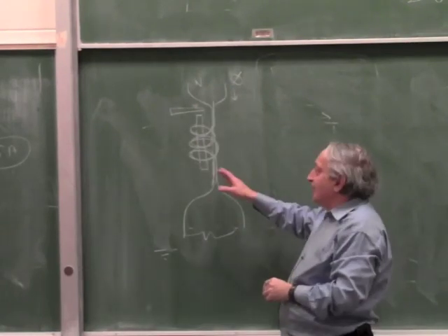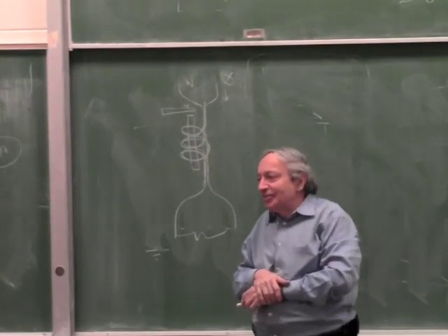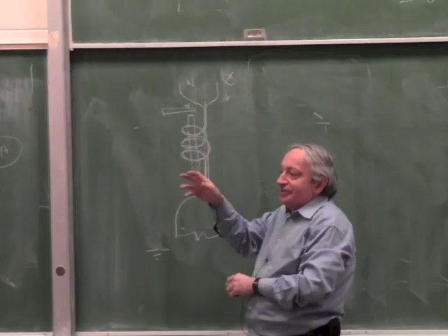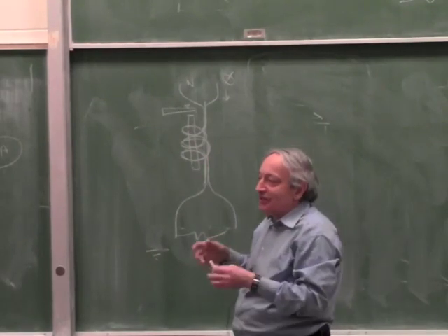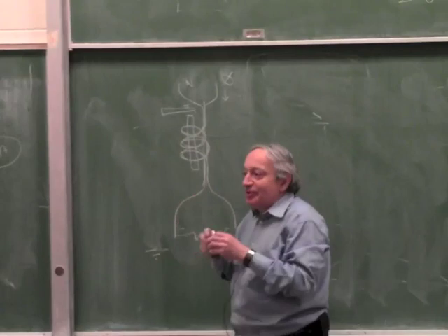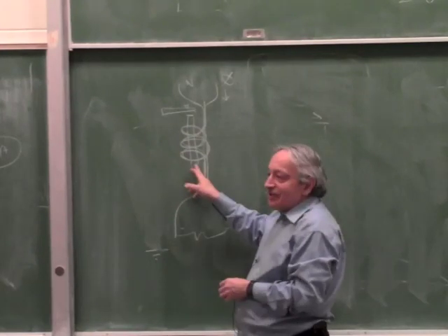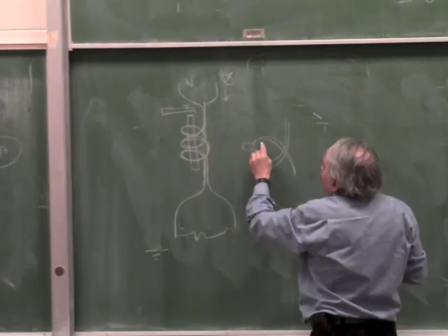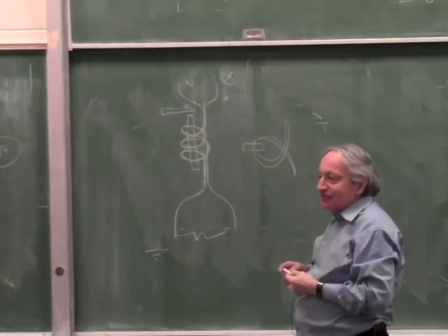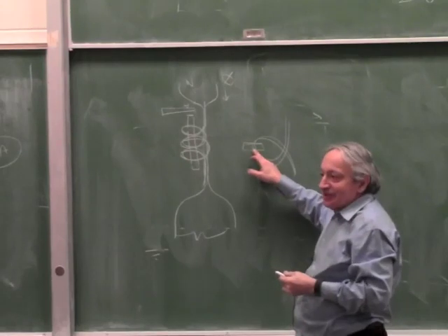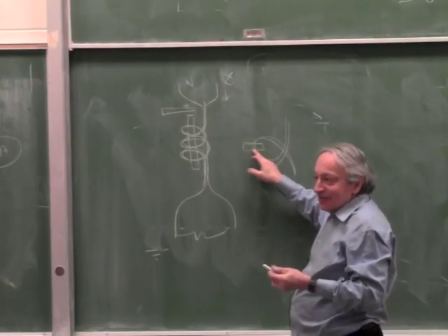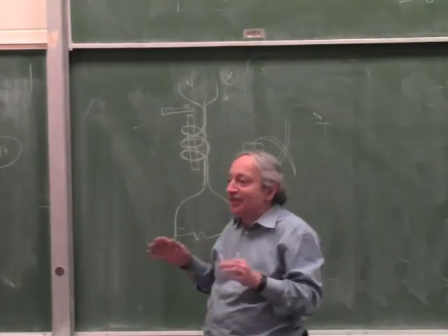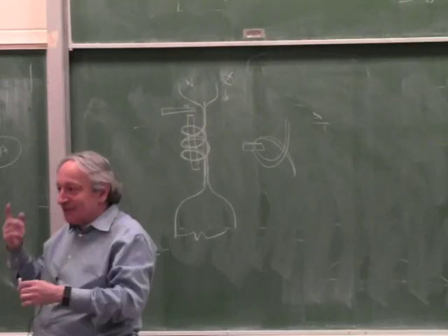Now, this is how it used to be done until about 5 years ago, but 5 years ago they got lazy making the coil, so it turns out it's cheaper to do it in a complicated electronic way than just winding the coil. So if you open the old ones, that's what they have inside. If you open the new ones, they have one turn and they have some much more elaborate magnetic field sensor, which senses the magnetic field is zero, like a Hall effect or something. But the principle is the same. The principle is you run the two wires as one wire, it should have no magnetic field as long as the currents are equal.